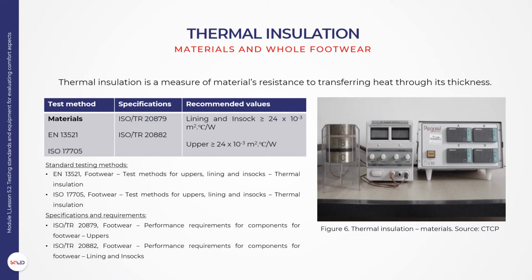The heat source is switched on and the temperatures of the 3 blocks allowed to reach equilibrium. The thermal conductivity of the test specimen is then determined from the steady-state temperatures of the 3 blocks, the exposed surface area of the blocks and test specimen, and the thickness of the test material.